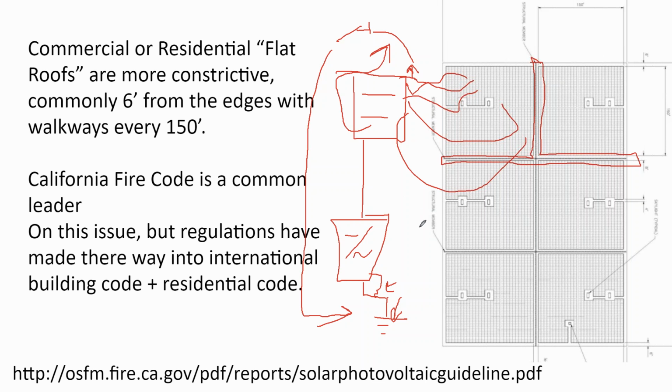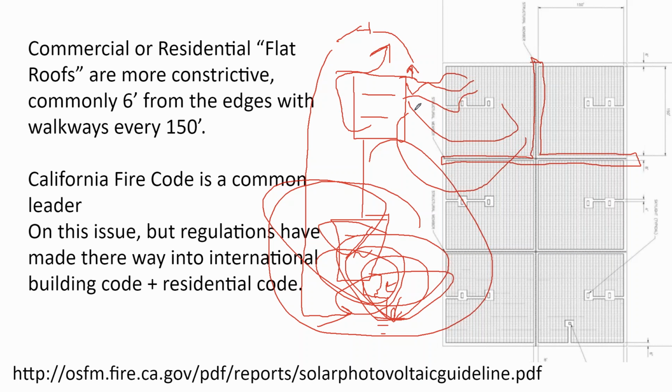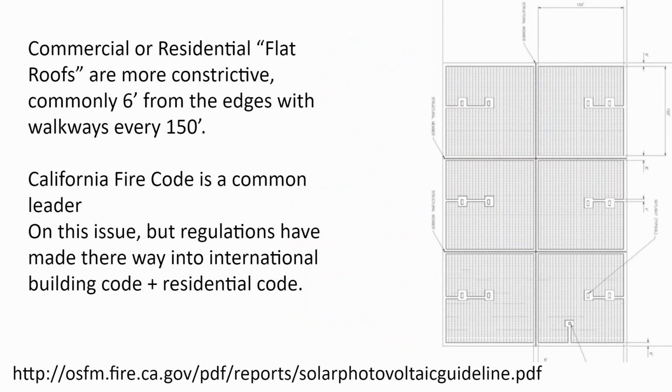And so most solar installers say, well, yeah, but now they've reworked this ground fault detection so that the inverters are no longer negatively grounded and instead are floating, and they've redone the ground fault detection to avoid that. And what that discussion completely ignored was how the ground fault up on the roof, up on that combiner box, began in the first place. Now, we know why it continued because of this blind spot in old school commercial inverters, but what caused it to begin with?